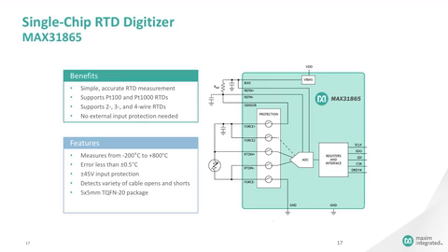It also detects a variety of fault conditions, such as opens and shorts. Incorporating these fault detection functions can be fairly tricky to implement on a measurement circuit based on a discrete ADC. So while the basic measurement circuit might be fairly straightforward, the implementation of a complete measurement system, which includes the fault protection and detection features necessary to survive in real-world applications, is much more of a challenge. The MAX31865 offers an accurate, reliable, and proven solution which is easy for the customer to quickly incorporate into his system.